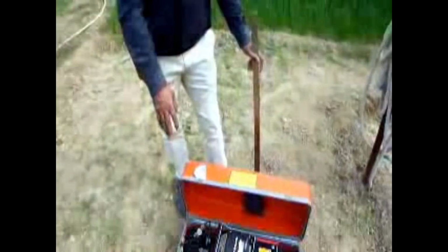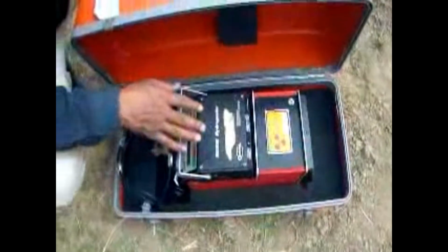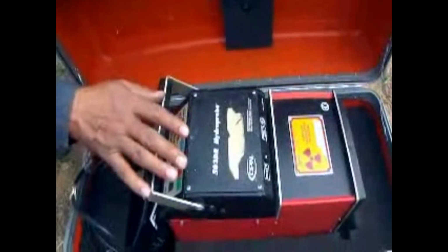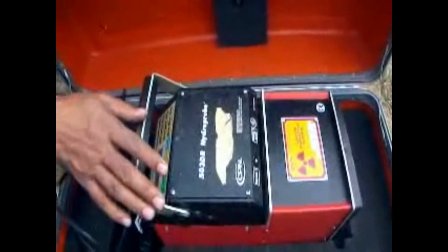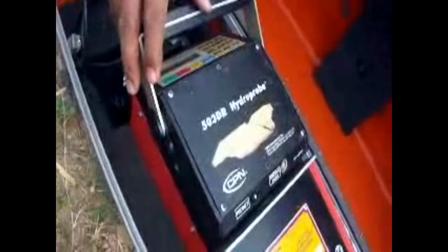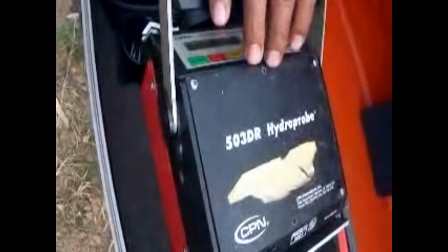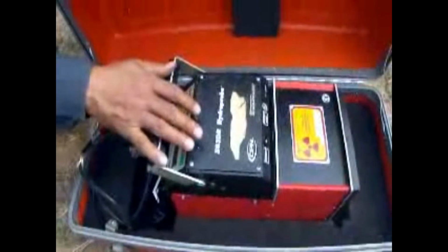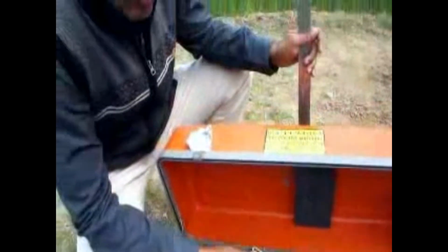That is basically by using a tensiometer. But you know that a tensiometer has a limit, 0.8 atmospheric head is the maximum we can measure. So let us see first, this is the oldest method and it is obsolete now. It is not used now, or not supposed to be used now, and this is the hydroprobe or neutron probe. Basically we have very low capacity neutrons.